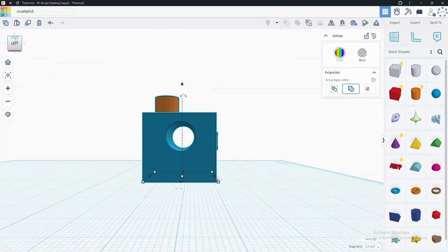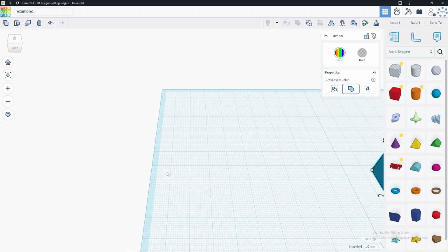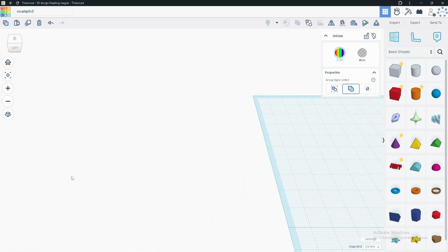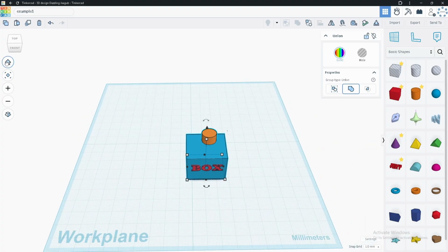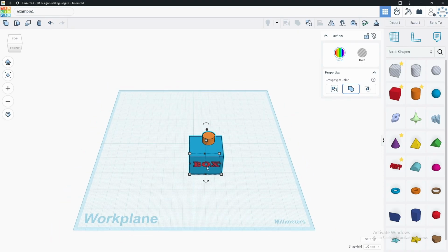Now, if something goes kind of crazy, I'm going to click my scroll wheel. It's called the center click. And I'm going to pan over here. I'm going to push my work plane away. If something happens like this, just click on the home view button, right? Over here under the cube, and it'll swipe you back to where you're supposed to be, right? That's the easy way to get back to the home view.